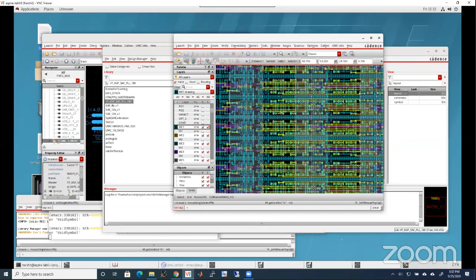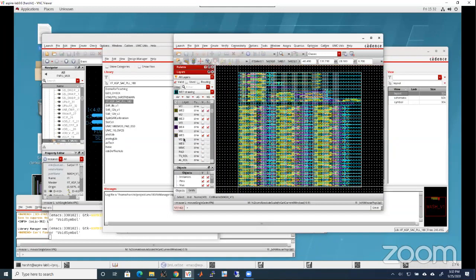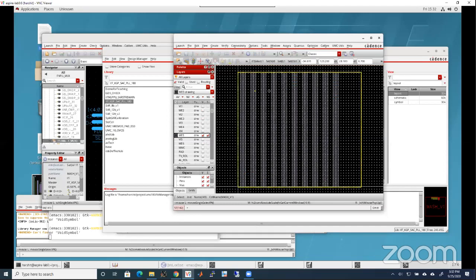And then final power delivery is done using metal 6 and metal 5. Metal 5 is used to do the power delivery. So if you see, the final power delivery is done here. And we have put the labels VDD, VSS, VDD, VSS all. I hope this clarifies the overall standard cell design. Any questions on this?